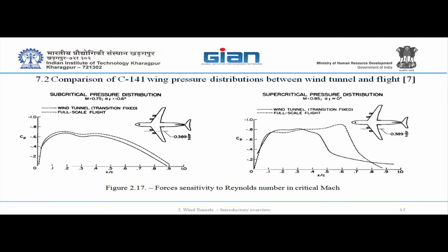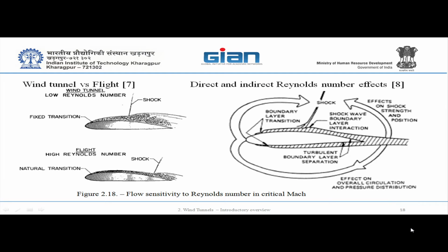So, why is it not reacting? We went left. Okay, so look at the flow. What happens there? On the left plot, once we fix the transition at the leading edge, we initiate the transition of the turbulent boundary layer, and because of that, it grows and it influences the flow.